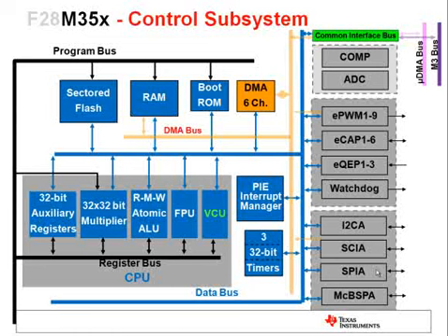The control engine is based on the C28X plus floating point processor, which supports IEEE single precision 754 floating point operations. Native floating point brings many advantages, not only performance-wise. Floating point is more robust, meaning it is less error-prone than fixed point math. It can also do the same math operations or functions as fixed point with significantly fewer instructions, resulting in easier development and faster time to market.